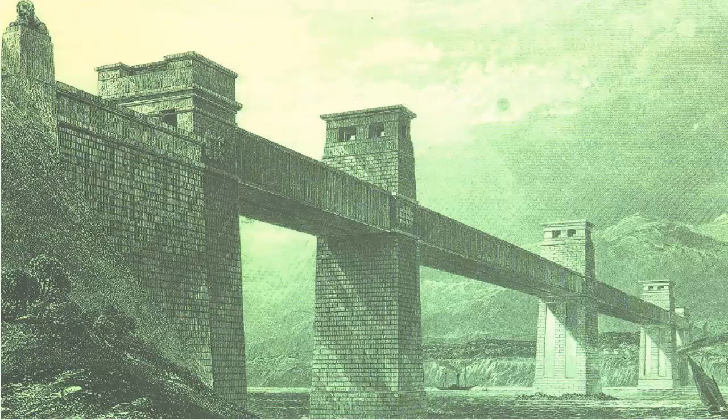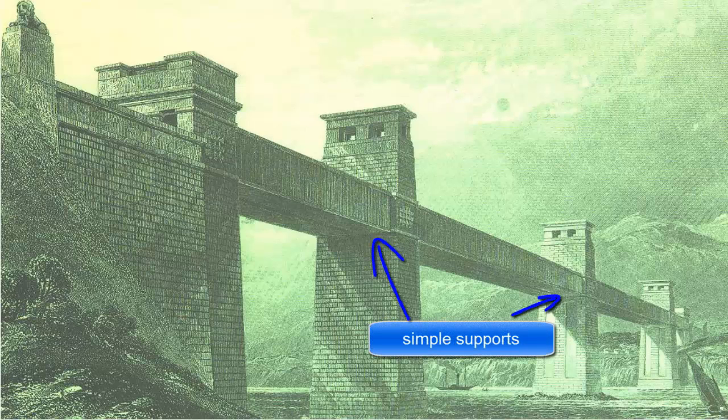A railroad crossing was needed over the Menai Strait in England with a long span. This double bridge was built to provide one track in each direction. The bridge was actually created with box girders. These are long hollow tubes with a rectangular cross-section. The trains run inside the tubes, and each tube is on a simple vertical support at each end.